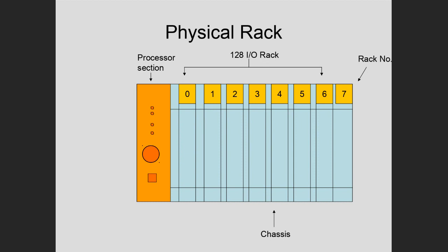This is hardware. Remember in the last class we talked about virtual devices? So we have real-world devices. The main ones used with PLCs, the most common one is, of course, a relay, either a control or a logic relay. But then there's also timers and counters. You can have a PLC mimic those in memory. And when we mimic a relay or timer or counter in memory, we call that a virtual device or logical device. Well, it turns out we can do the same thing with a whole PLC rack.